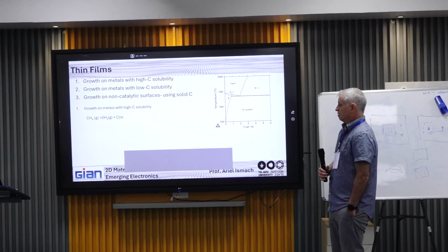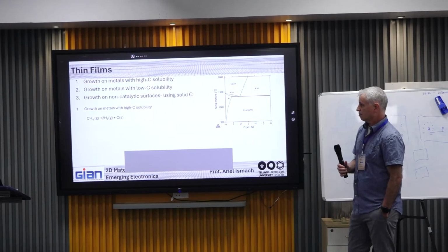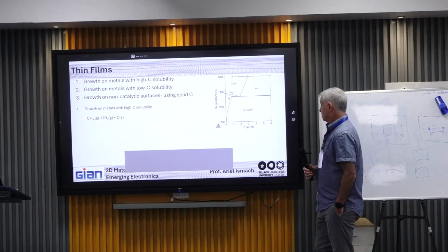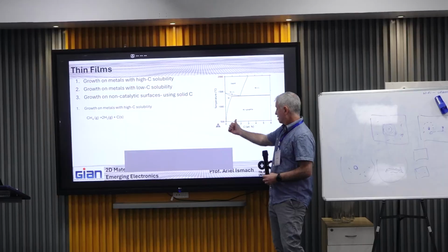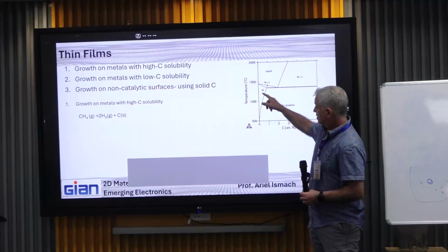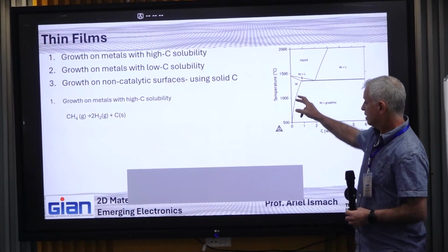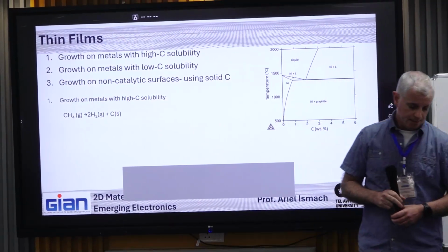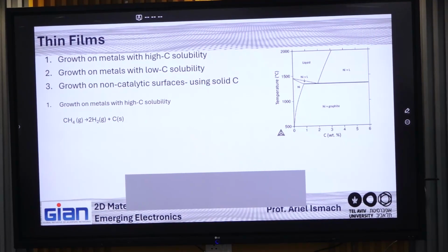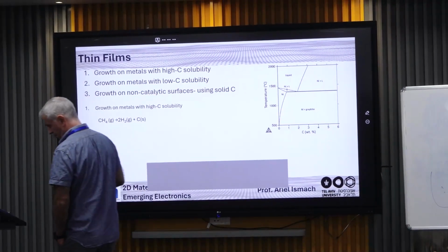In this case, carbon, which is the element that you need to produce graphene, of course, and nickel, which is the catalytic substance. And you see from the phase diagram, with carbon concentration increasing and temperature, that you have a region in which you have relatively high dissolution of carbon into the nickel. Okay, so keep in mind that. You will see why I'm talking about this.